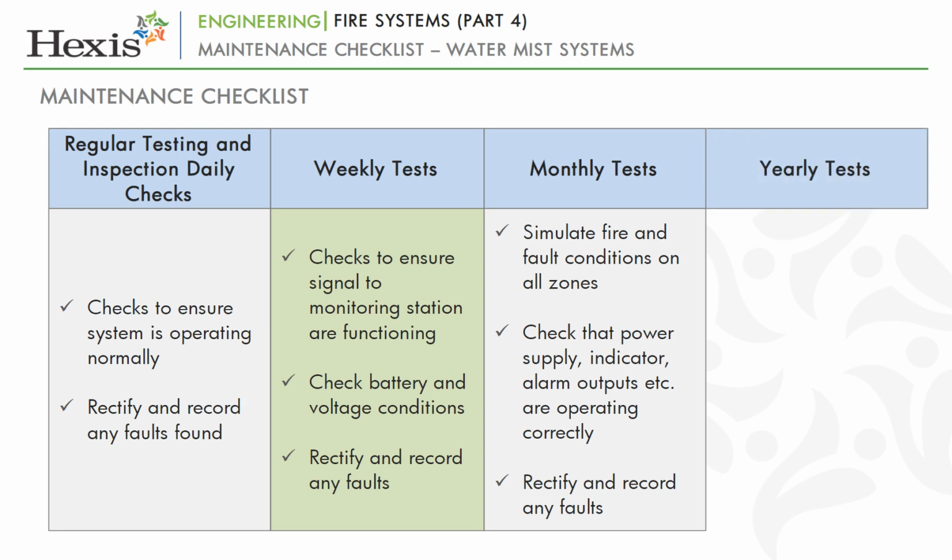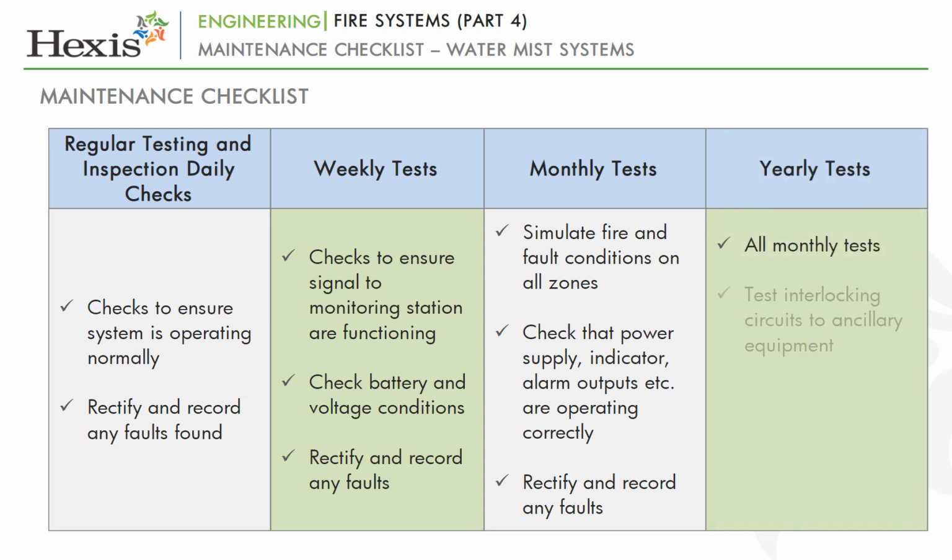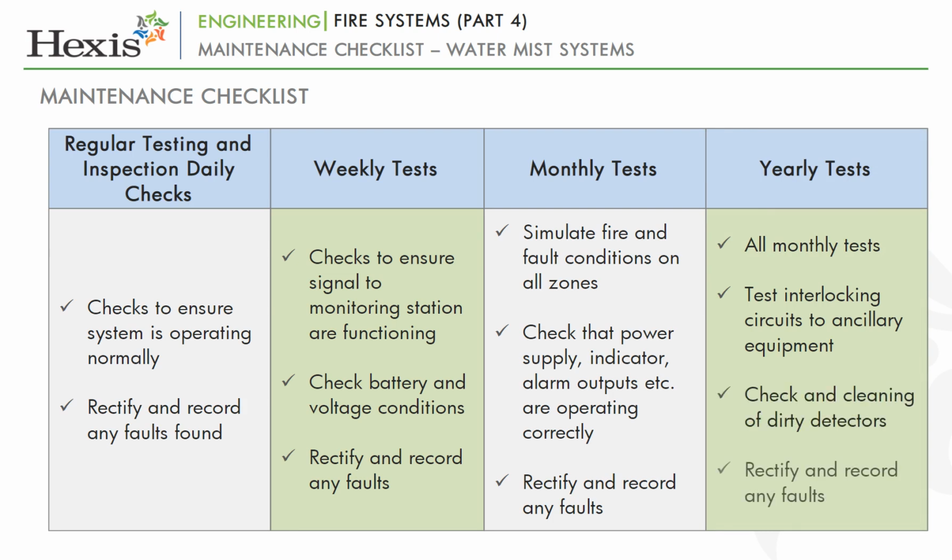Yearly tests. All monthly tests. Test interlocking circuits to ancillary equipment. Check and clean dirty detectors. Rectify and record any faults.